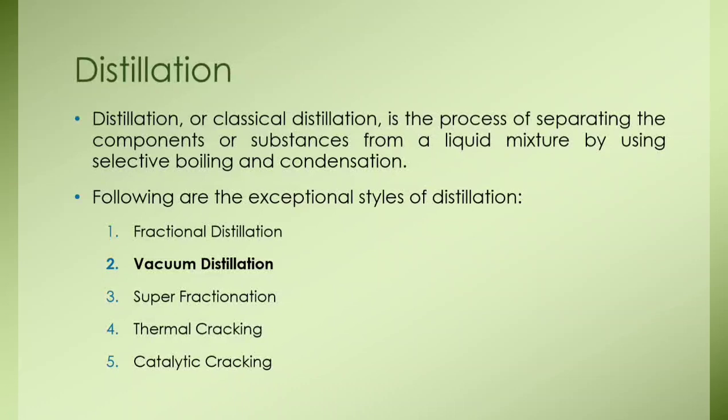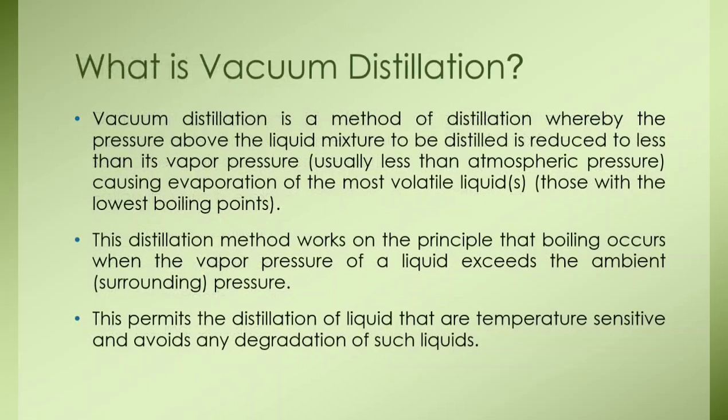It is a process of separating the components or substances from a liquid mixture by using selective boiling and condensation. There are the following exceptional styles of distillation. First is fractional distillation, then vacuum distillation, superfractionation, thermal cracking, and catalytic cracking. Among these five, we will mainly focus on vacuum distillation only, as it is the part of this presentation.